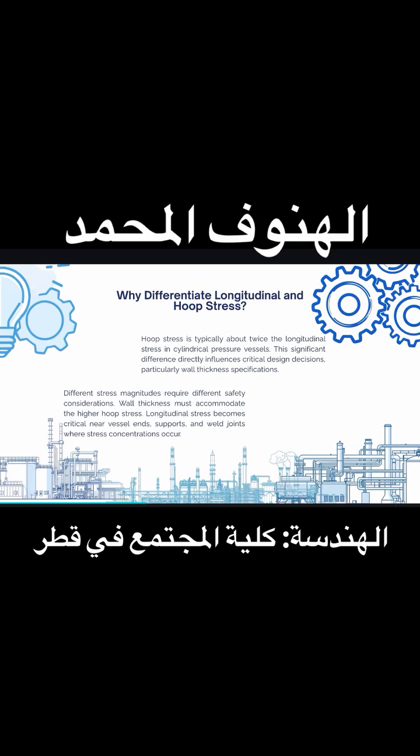Why the difference between longitudinal stress and hoop stress? Hoop stress is typically about twice the longitudinal stress in cylindrical pressure vessels. This significant difference directly influences critical design decisions, particularly wall thickness specifications.